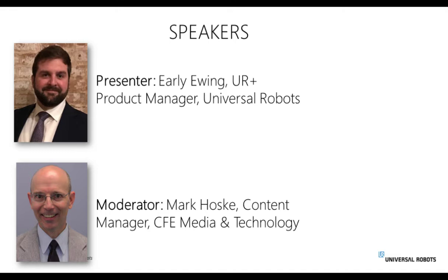Well, I would say the considerations are the same as any other piece of equipment. What's different is how to satisfy those concerns through the controls and the features inherent in the robot. Good point of reference, and the Collaborative Robot Industrial Safety Standard is TS 15066. And if there's specific questions about that, we can address it offline. But really what the robot's doing is giving you greater ability to solve that.